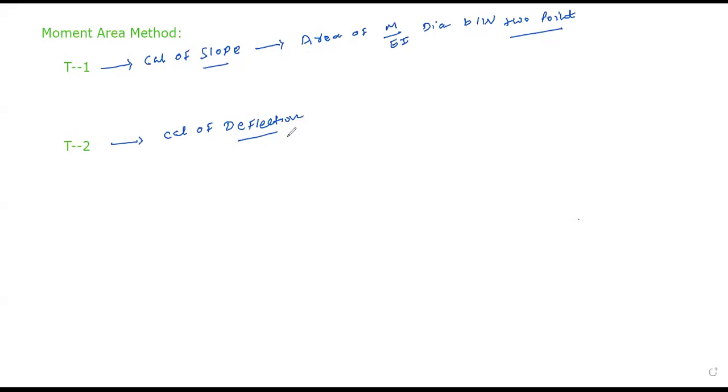And in case of calculation of deflection, we will calculate the moment of area of M divided by EI diagram between 2 points.